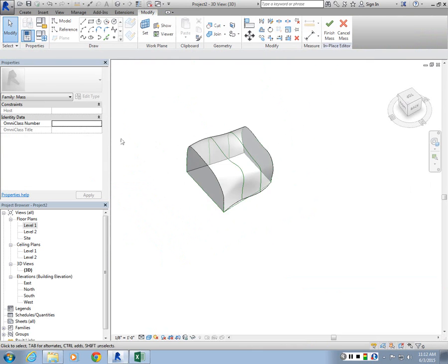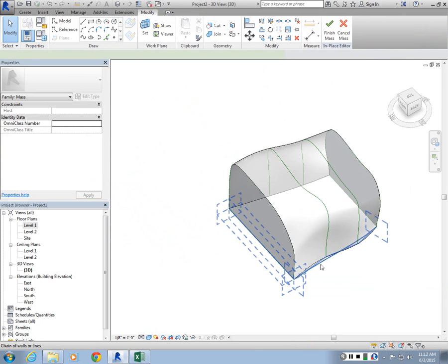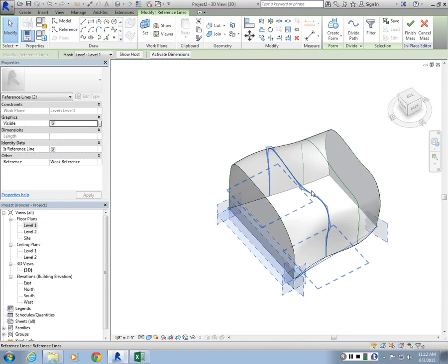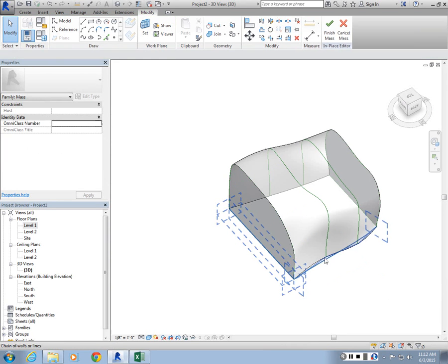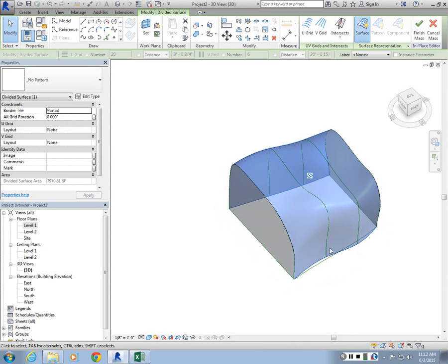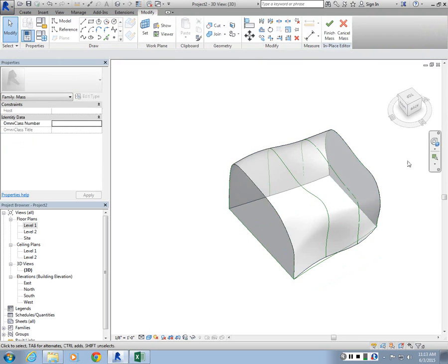To be honest, I didn't try doing this yet. This will be a blobby shape, and I don't want you to do blobby shapes anyway. I just want you to do something smooth and simple. Because it also depends on what you want to extract. If you want to do just an envelope type of surface and do like louver treatment on it, this will be a good fit. But if you want to extract also floor slabs out of it, it has to be a mass. It has to be a closed volume.